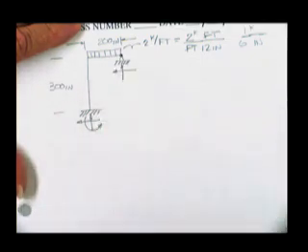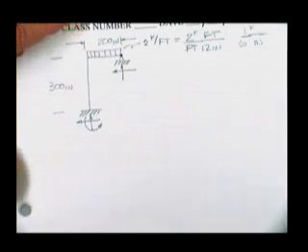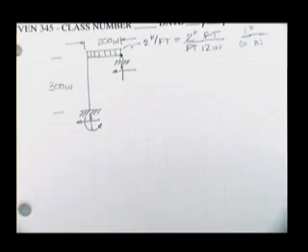There are 5 forces acting on the exterior surfaces of this, and I was only gifted with 3 equations of statics. In fact, that's all I gave you. And so we are 2 degrees statically indeterminate.